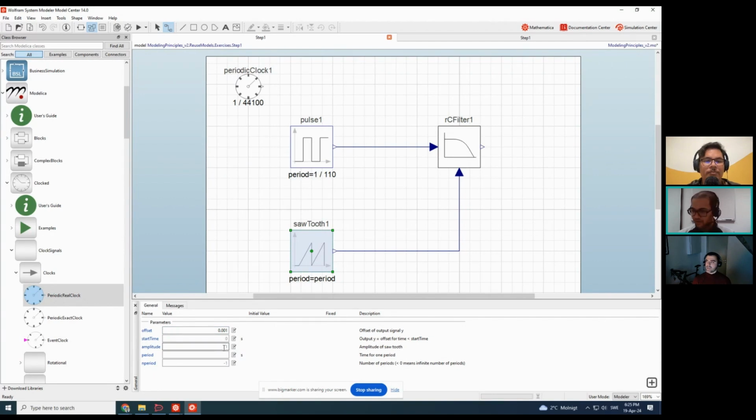Sorry to interrupt you, Ankit. Helmut is asking why don't we need an amplitude? Because we need an amplitude, but we don't set it to a different value. By default, the amplitude value is set as 1. So if you don't register anything, it will be considered as 1. So we are considering 1 volt, and we are keeping the default value for now. Of course, depending on your circuit, you can change it, but for this exercise, we're keeping the amplitude with the default value of 1, right?